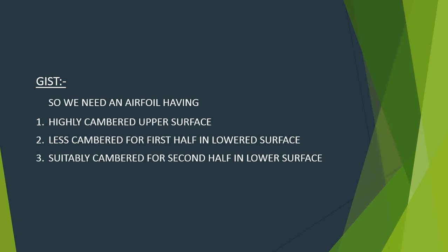Now what is the difficulty we are facing in that? We need an airfoil having three things. First, a highly cambered upper surface. Second, less cambered for the first half of the lower surface. Third, suitably cambered for the second half of the lower surface.